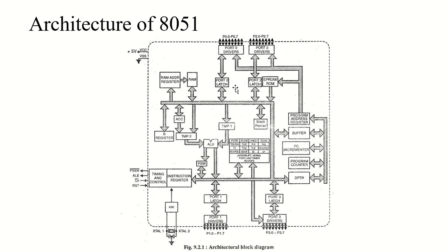And again, the timer registers are divided into 8-bit registers called timer low and timer high, TL0 to TH1. TL0 and TH0 combined form the 16-bit timer 0, and TL1 and TH1 form the 16-bit timer 1.